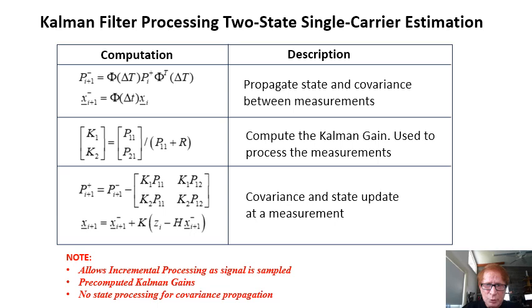As a final note, we show the residual process. This is the predicted measurement minus the actual measurement. We also show the predicted residual covariance. By monitoring the residual process as measurements are processed relative to its standard deviation, we can throw out bad data and we can detect when the assumed model has changed, as in the case of the presence of a discontinuity from a multipath delayed signal component.